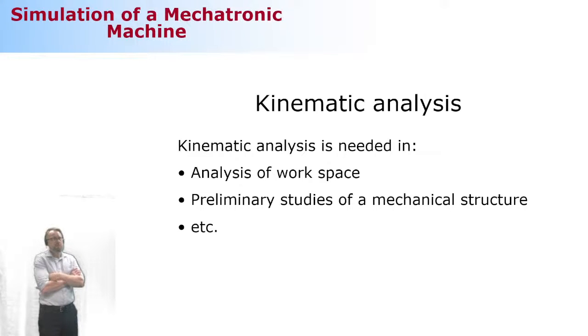Kinematic analysis is the art of motion. It's not about the forces. We discussed this earlier. The forces are off the game when we have kinematic analysis. As a post-processing procedure, if you are really interested, you can figure out the forces too. But as an analysis type, it is only about motion: position, velocity, acceleration levels.